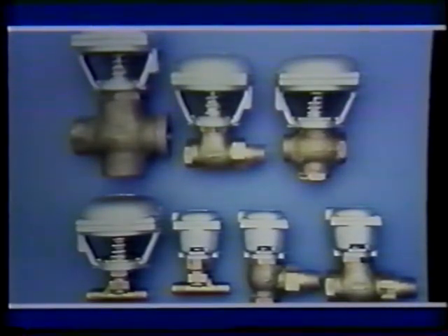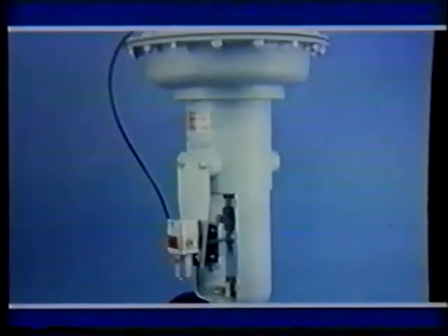Two-way valves and their actuators come in a variety of sizes. Shown here are a few of the valves available with their body and actuator configurations. Valve body sizes range from 1/2 to 4 inches, with actuator sizes ranging from 3.5 square inches to 80 square inches for the larger models.